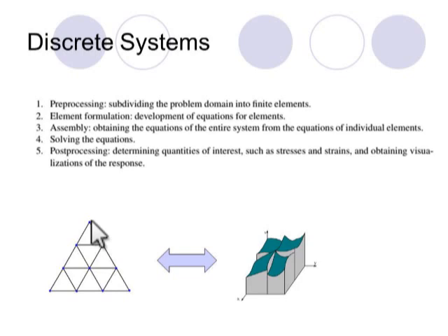Therefore, we need to make an approximation of the variation of the displacement, and in fact we know from numerical methods we use polynomials in general, or functions, for the interpolations, right? So then we say that within the element, the property that I'm interested in varies with this function.